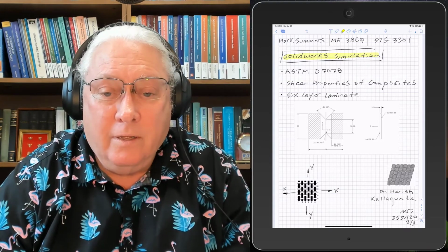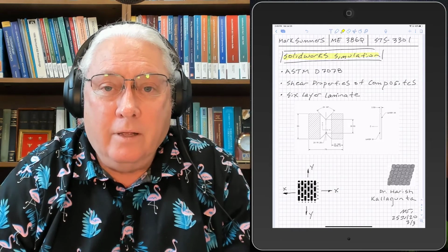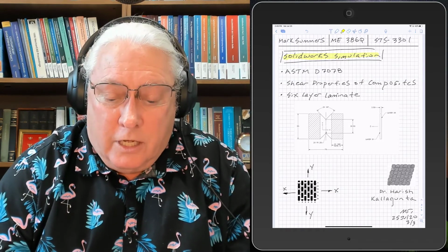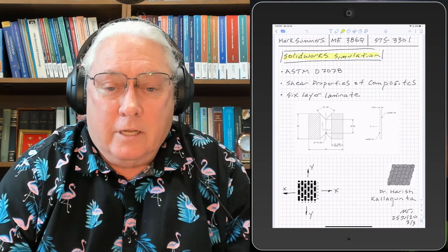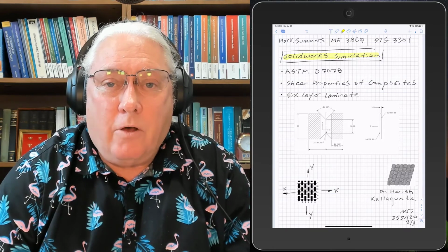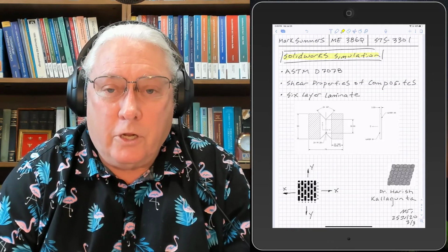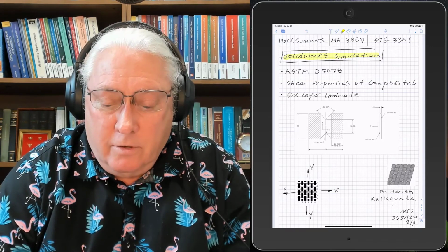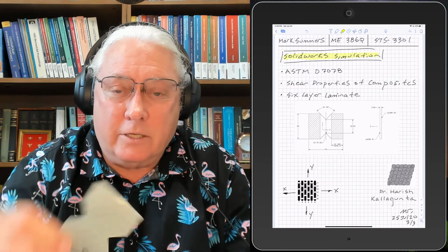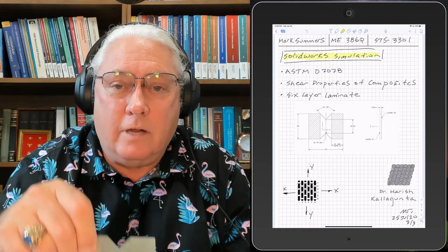that interlaces with the two. And so it turns out that for this particular test, this Young's modulus in the X direction and Young's modulus in the Y direction, Young's modulus in the Z direction, we're going to input all 3 of those parameters, but 2 of them are going to be equal. Young's modulus in the X and Young's modulus in the Y is the same because it looks the same whether I rotate it 90 degrees or not.